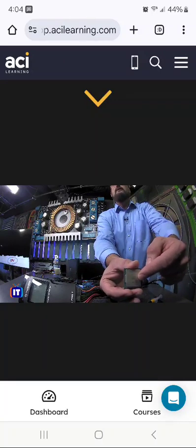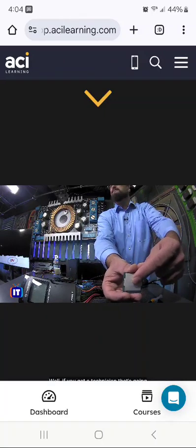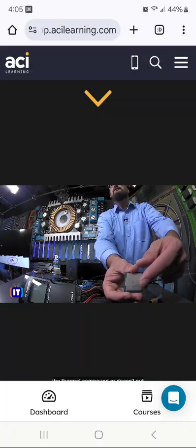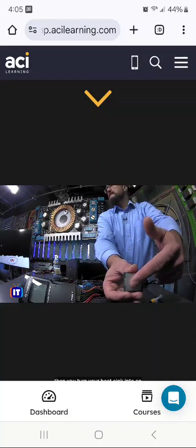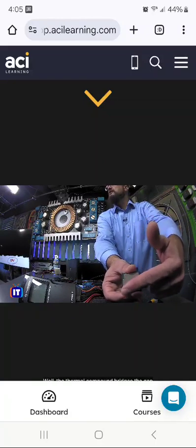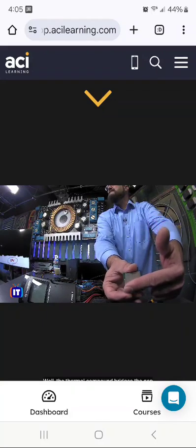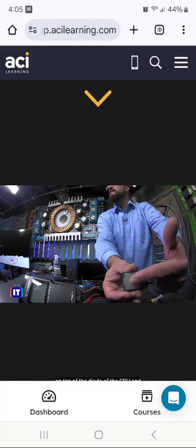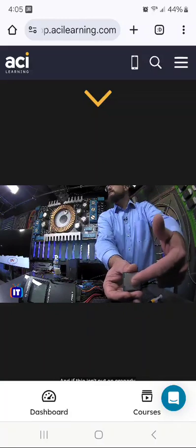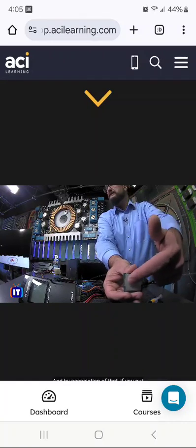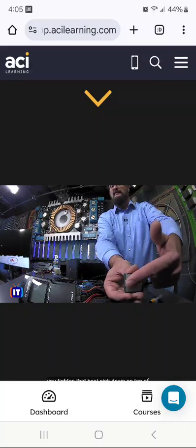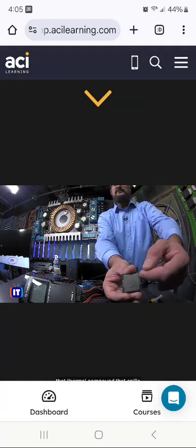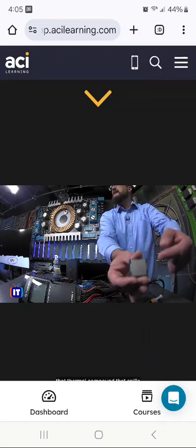Now, that's important. Why is it important? Well, if you get a technician that gets going a little bit too fast and doesn't put the thermal compound, or doesn't put it adequately on there, then you turn your heat sink into an insulator, because you have metal on metal. Well, the thermal compound bridges the gap between the inconsistencies of the metal on top of the die of the CPU and on the bottom of the heat sink. And if this isn't put on properly, then we can have overheating issues too. And by association, if you put too much thermal compound on this and you tighten that heat sink down on top of the CPU, you could actually have some of that thermal compound spill over into the sides, into the socket.